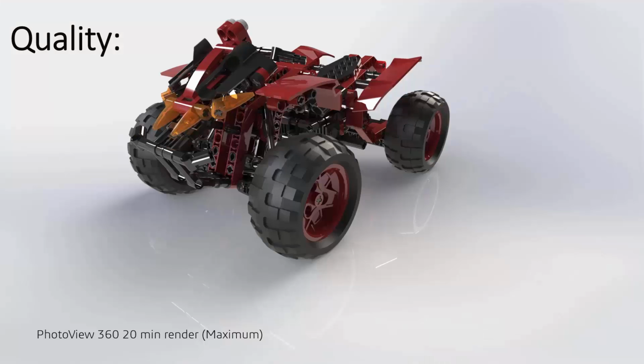Hey guys, I just want to put a pause in here real quick. When I did this session, when I came back and looked through it, and reviewed this a little bit more, I think I might have given PhotoView a slightly unfair shake here. When I rendered this 20-minute render, it was on maximum quality, and I was thinking I was on best quality. Let me compare these real quick, because I mentioned that you just couldn't get a quick render out of PhotoView, and that's not entirely true all the time, because you can turn the quality settings down for quicker renders.